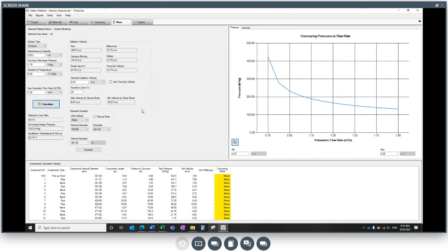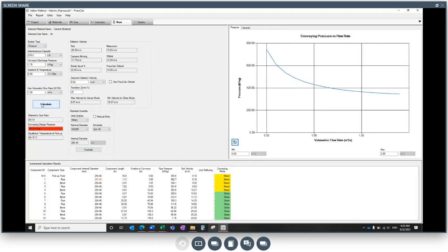So I've set out my maximum required pressure, and then I will reduce my pipe size. So I'm going to use my master override tool here and change my system from a nominal system of 400 for the screw pump to about 250. I'm going to override my piping geometry and press calculate again. And now let's look at what we have.